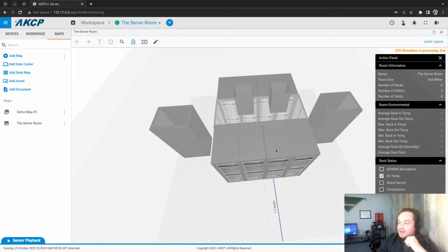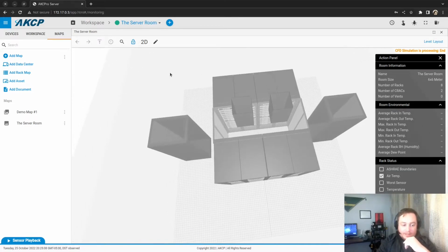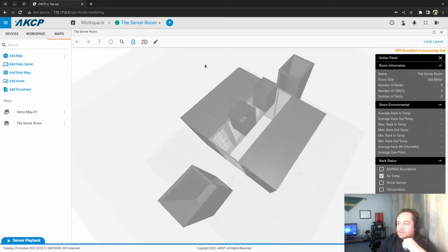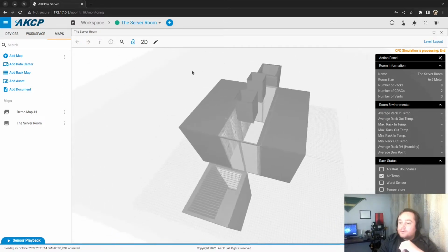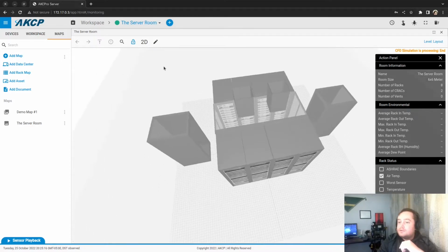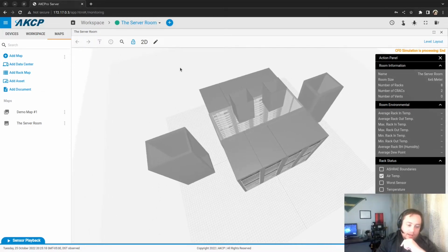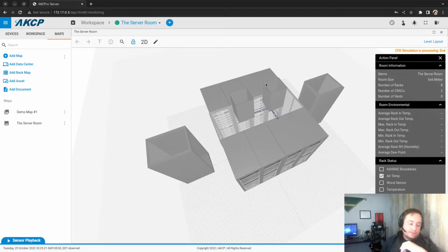So the simulation is starting, and it depends on the server you put the CFD server on. For a small room like that, it can take 2 or 3 hours. So you can do any other thing. Everything is automatized. The software will do the drawing, the meshing. It will set your boundary conditions.